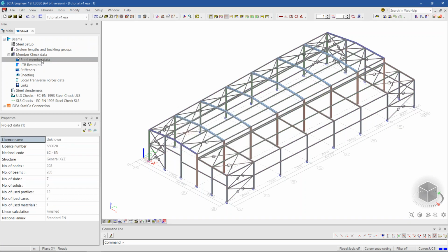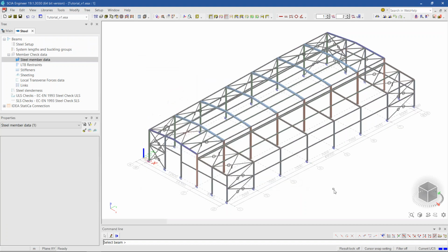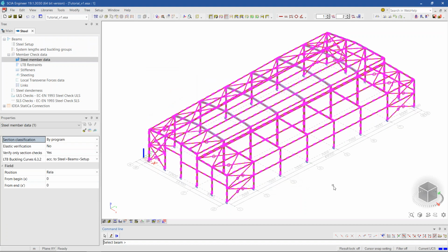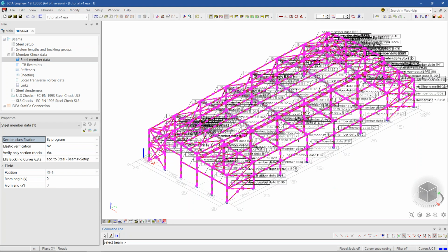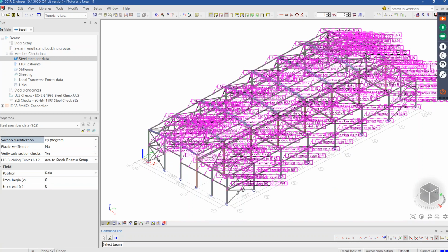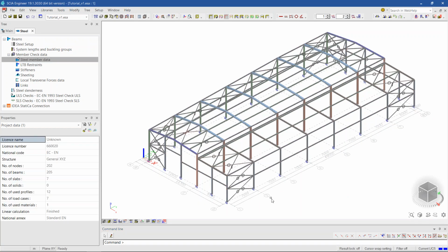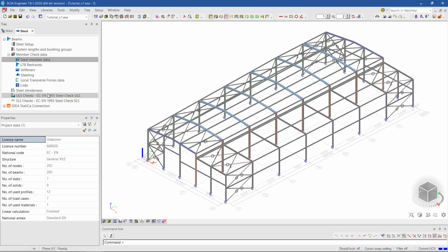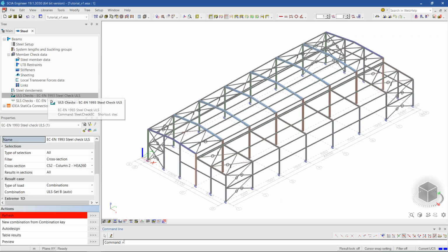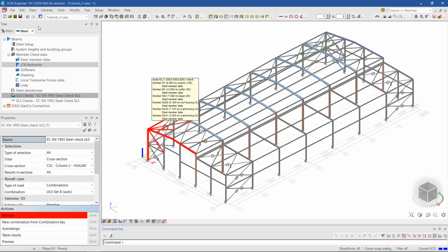Excuse me for the error. So I will apply this when nothing is selected, then I will select all, and then I will apply this data to the model. Usually this option is very suitable when you are designing your bracing, but just for the purpose of demonstration, I will also use it on the whole structure. And so in this case, when I perform section checks only by member data, then I'm able to auto-design my structure. And I've even prepared a model here.